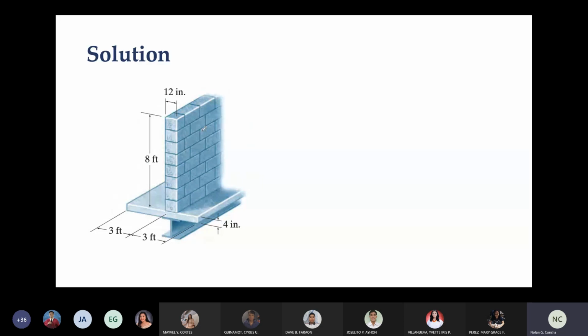So this is the beam, or these are the elements, and again, this is my 1 foot length. And I want to measure what is the weight of all these elements in that 1 foot length. So we start with the concrete slab. In the concrete slab, it's 6 feet in width, multiplied by the thickness, which is 4 inches, multiplied by 8 pounds per square foot per inch of thickness of your slab.